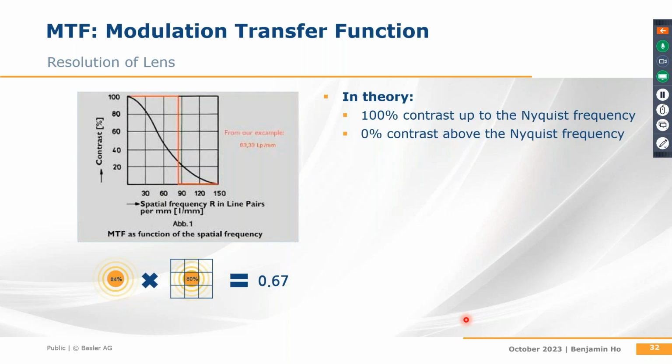The first concentric circle occupies about 84% of the entire Airy disk. And the lens manufacturers have decided that accommodating a specific pixel size is sufficient if 80% of the first concentric circle is within a pixel. Therefore, since only 80% of the first concentric circle, which makes up 84% of the whole Airy disk, needs to fit within a pixel, the factor of 0.67 is applied to the final calculation of this criteria.